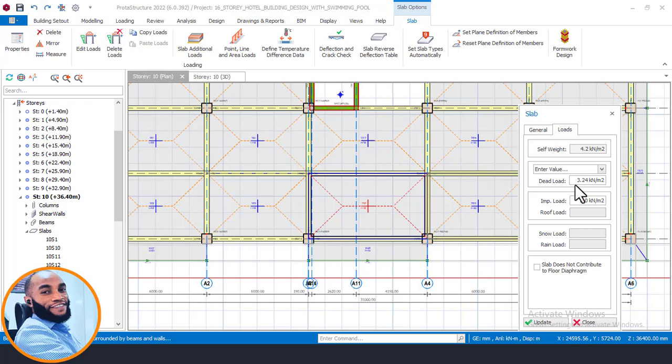324. Yes, 324. That becomes my dead load based on the soil, knowing that the soil unit weight is 18 kilonewton per meter cubed, and all that. So we have to factor in that value, and then we got 3.47. You can go and find out how to calculate all that. Okay, so I'll come here right now and then click on what?